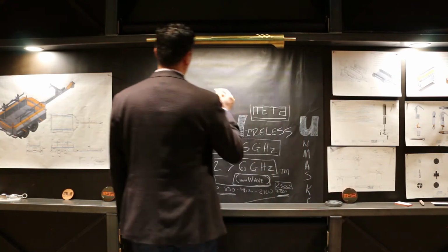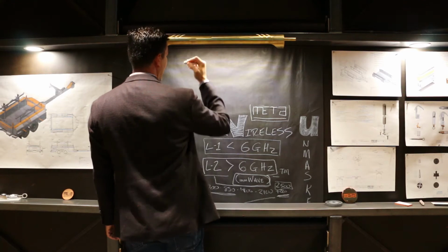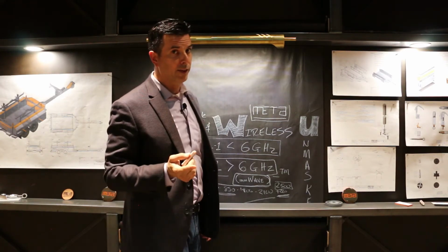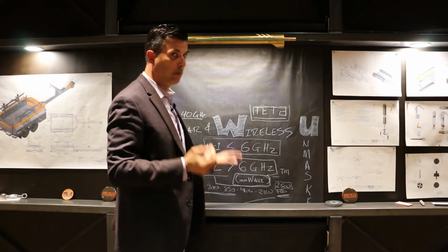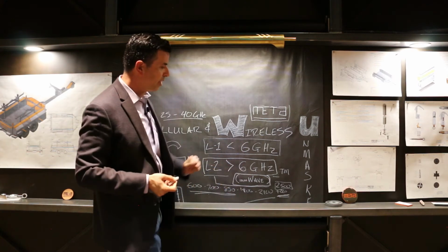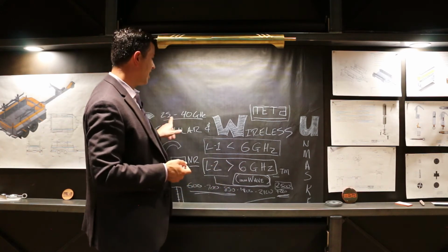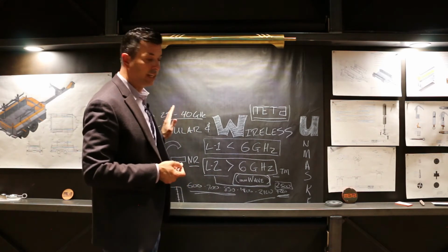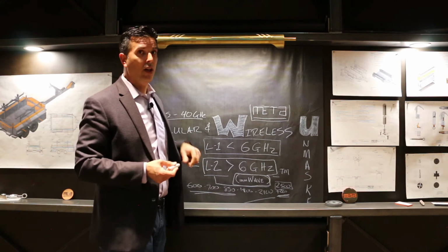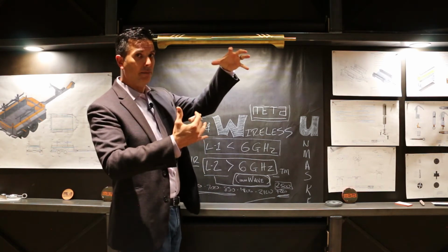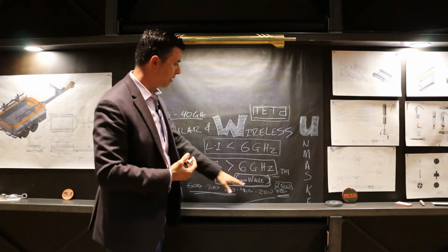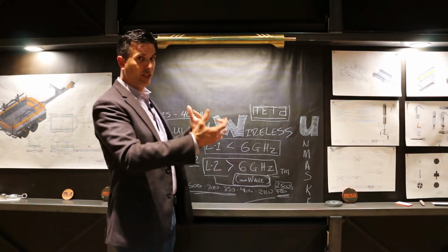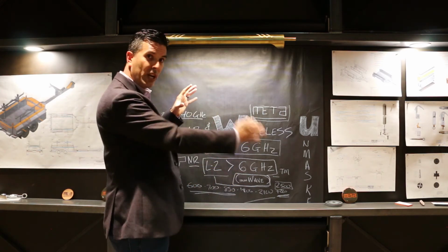What you'll see on a lot of small cells and the millimeter wave deployments are small cells. Why? The millimeter wave high frequency, 29 to 39 gigahertz, 25 to 40 gigahertz, this range, they don't propagate very well. You can't have that mountaintop macro site because the millimeter wave attenuation in free space is so high it won't reach the end user.